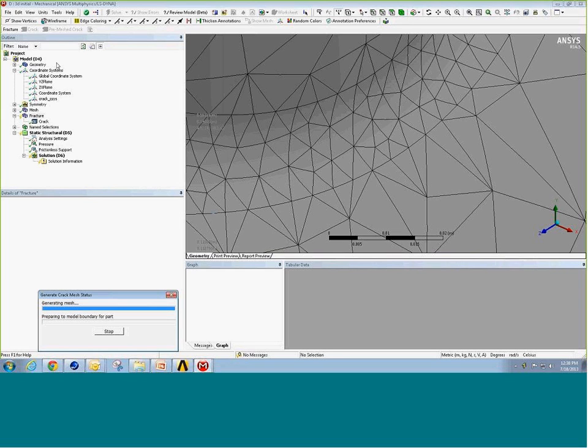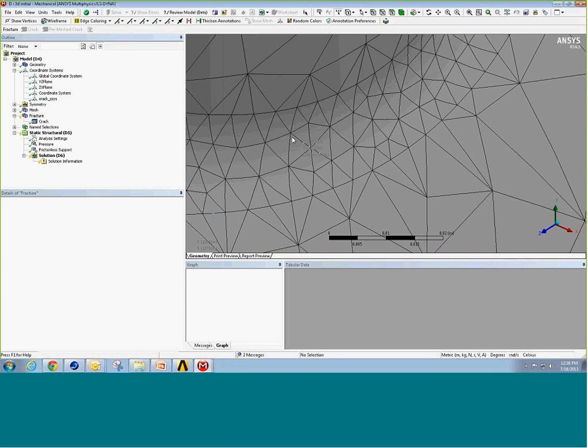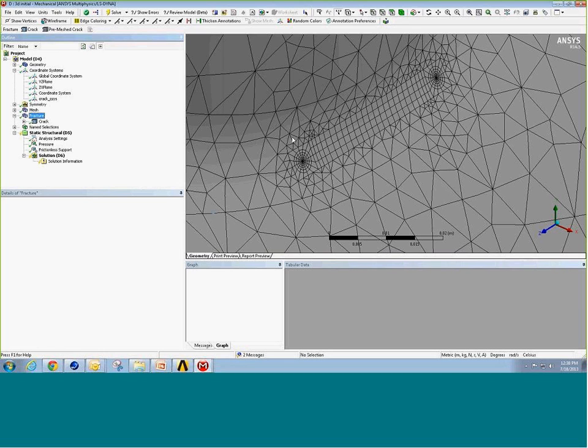If you notice before when I was doing this, not only did it show where the crack was located, it was also showing a nearby block. That's called the transition region. Essentially the code is going to use the mesh from far away, and it'll mesh what you want right at the crack tip, crack front, but in between it uses a transition zone to hook the global mesh up with your crack mesh.